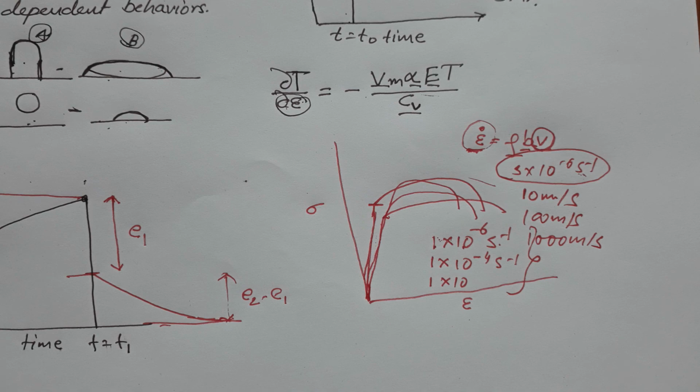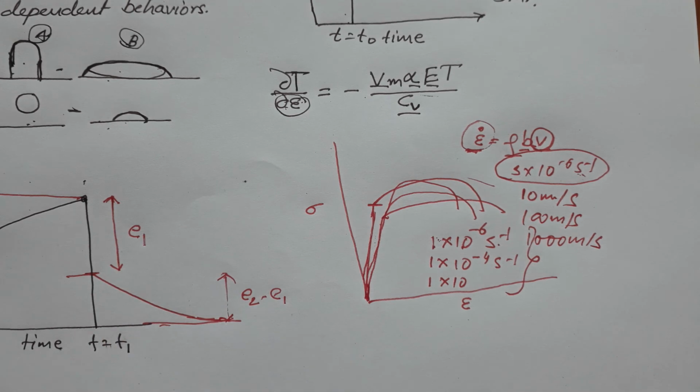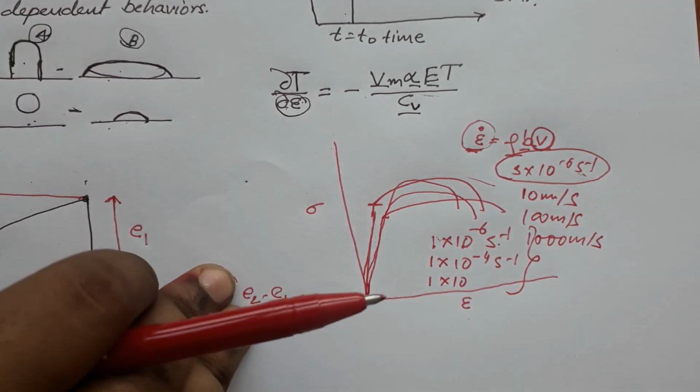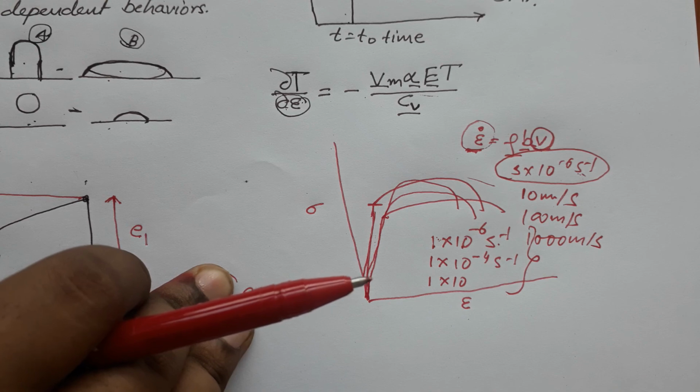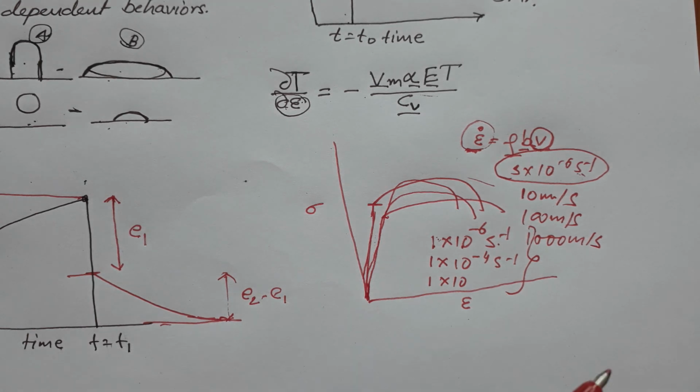So here what we talk about is called the thermoelastic effect. That there is a change in temperature and there is a change in elastic strain if you allow the time, is called the thermoelastic effect. And this is different from what we are going to talk about, because we are not only going to talk about the elastic effect, we are going to talk about deformation which is permanent and which is time dependent. So this is not creep, this is the thermoelastic effect.